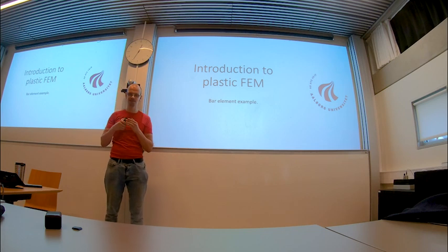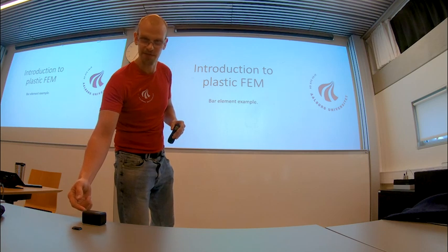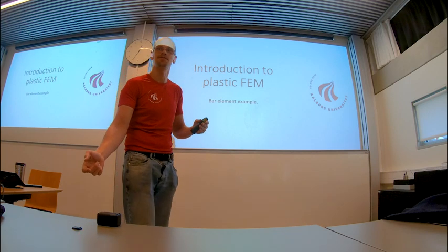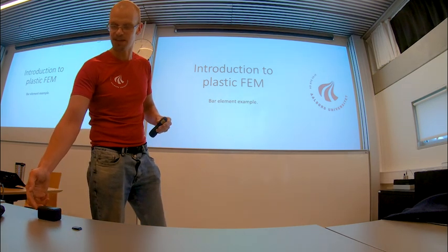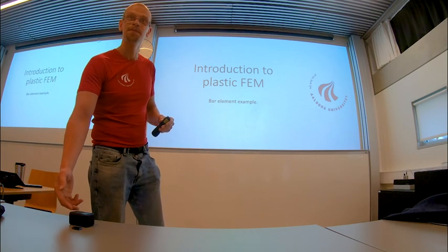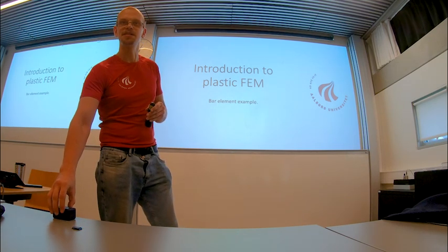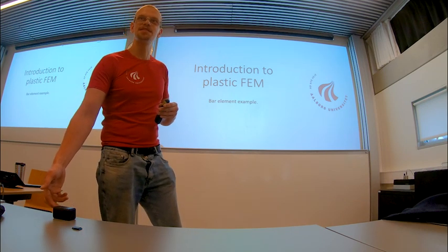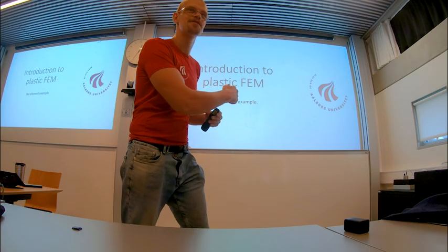If you apply a force, you can imagine this box here is a nonlinear system. There's some stiffness, and then if I push it too hard, it moves. And the deformation stays. So it's plastic deformation right there. You can push your laptop on the table, for example, and you will notice that you can touch it, there's a reaction force, and then if you increase it a little more, it moves. Similarly, in simulations, if you apply a force and the physical system cannot generate the reaction force, what happens is the engine cannot find a solution. So you apply a force, it starts moving, and the engine just goes to infinity.